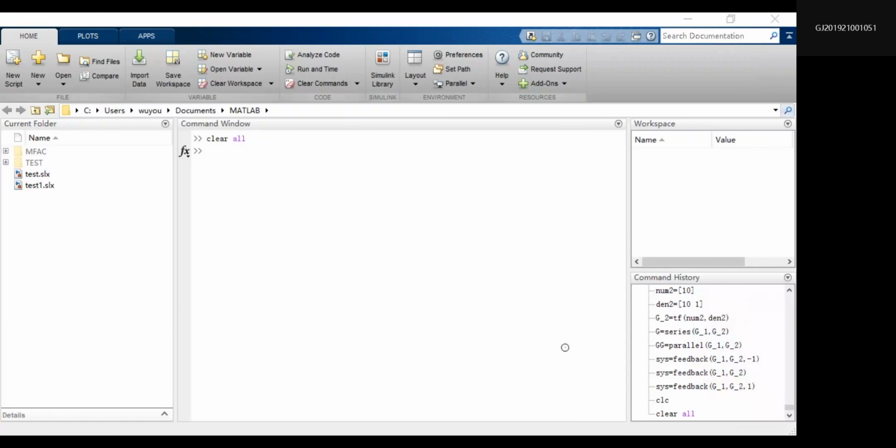And now we have feedback, but what we need is negative feedback. And here it says plus plus, it's positive feedback. How to change it? Click it, and we can change the parameter block. Here shows plus plus, right? You can change it into plus minus, and we see what changes. See here, we get a negative, right?